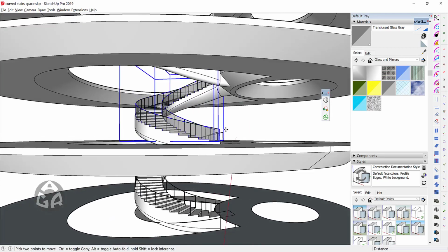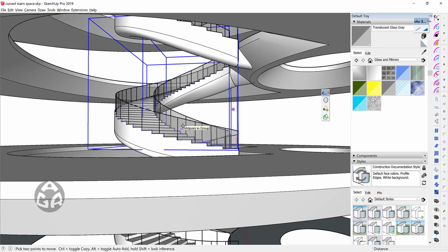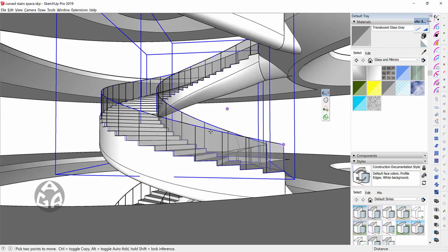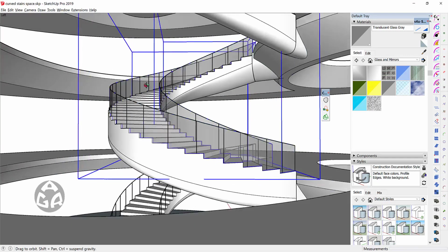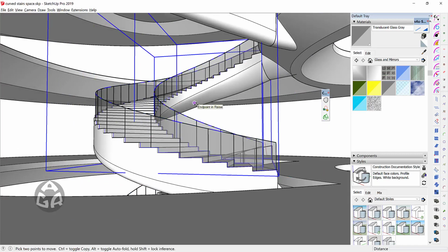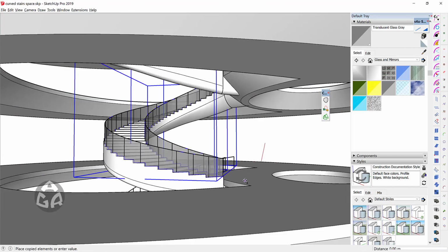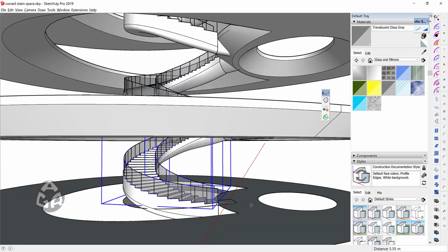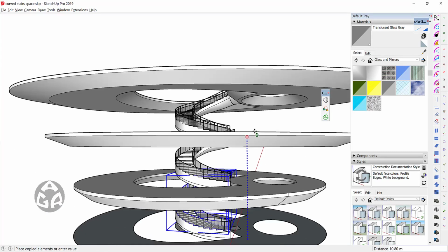So the S4U plugin would make the railings for you, the curves for you, so the rest is up to you. So you want to make like a loft along this path, or a follow me with a circle section, or you could use it like this to create a surface from these curves. And I would copy this one here and also here,